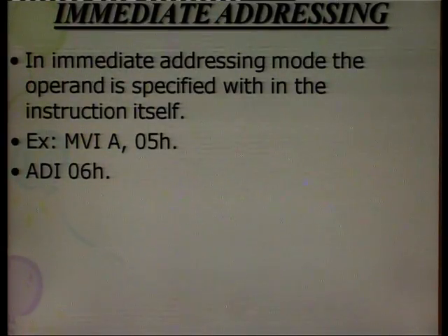Examples for this type of addressing. So, it is a valid way of mentioning data. An example for this type of addressing is MVI A, 05H. Here we want to store 8-bit data into the accumulator, that is an internal register. This is the most important internal register, and the data is 05.